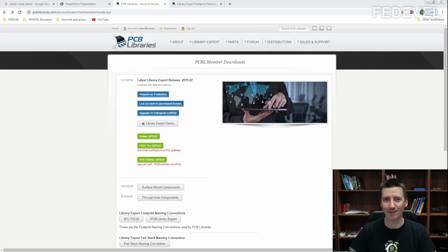Once you know what you need to be careful about, then you will create the footprint perfectly fine. You will use the proper pin names, pin numbers. But I remember the times when I was starting with hardware design, and most of the mistakes I used to make were in the pin names or pin numbers of footprints. I think everyone who is starting with hardware design goes through this process, and everyone learns the hard way. I really remember my mistakes: a DB9 footprint which was inverted, a SOT transistor footprint, 1 to 3, 3 to 1, a diode footprint. And yes, we all learn from these mistakes. It's nothing special if something like this happened to you.